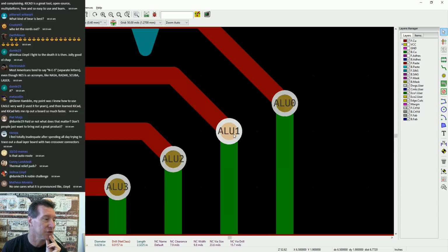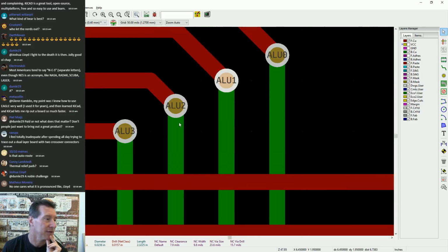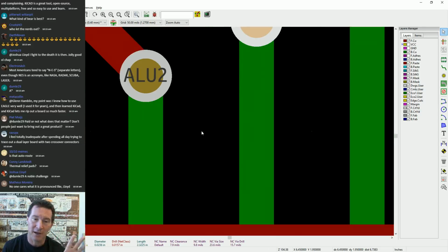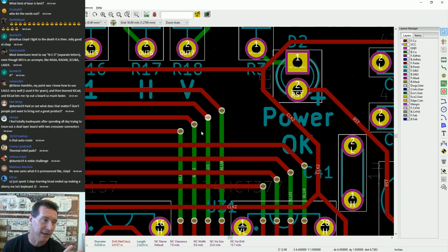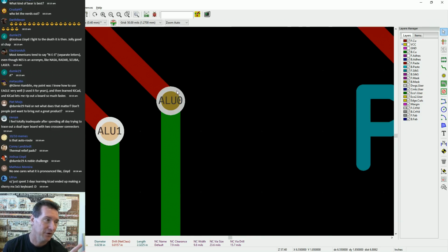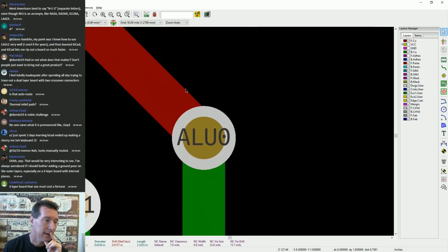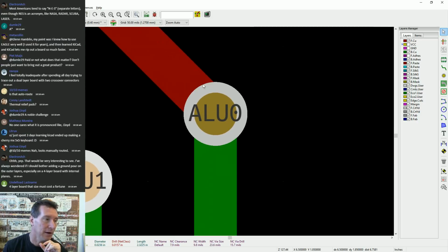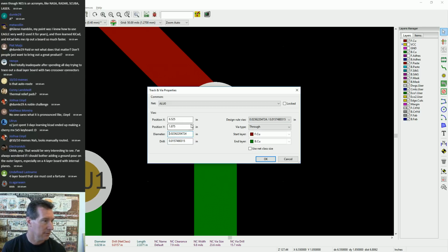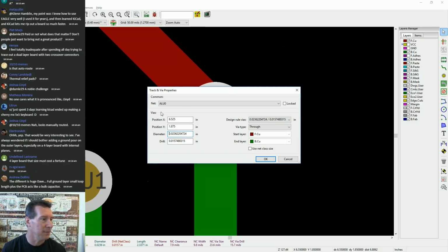We don't have much. Look at our poor vias there. But I'm not going to change anything. I'm going to leave it, because you risk a breakout there. The annular ring around the via, I don't know. I could go in there and measure it. There it is, in inches. I wish you could toggle between inches and millimeters in the dialog box.